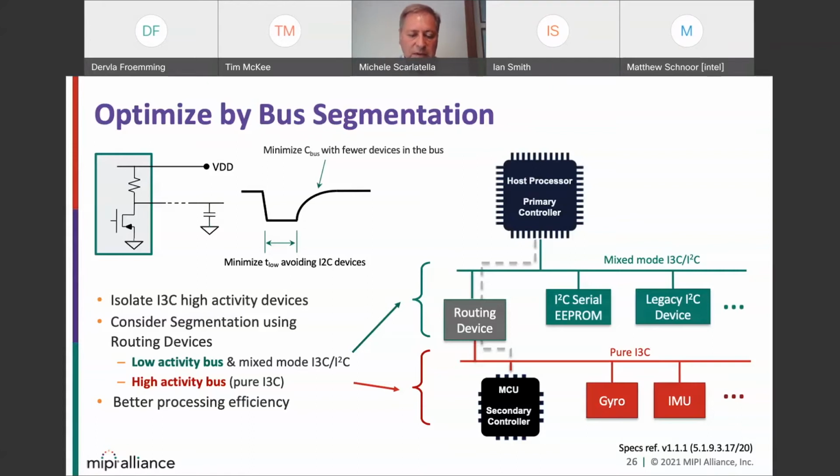So this is something that you could not do with other similar sensor buses. And you also keep the ability to access everything at a single level, because all the devices behind the router will be seen as a virtual device. So you don't lose any accessibility. So this is one way to design your system to benefit from I2C, keep the compatibility, and have low power.